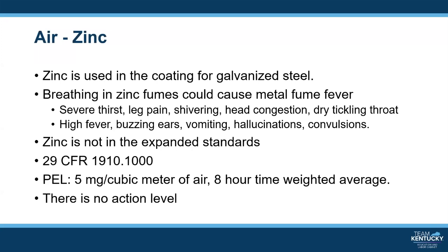Some of you may weld over a period of time and get used to these symptoms, and you may have actually built up an immunity to hide the full effects. If you take a break from welding over the weekend or over a holiday, the symptoms will often come back the next time you weld on galvanized metal. Because of this behavior, metal fume fever is sometimes called Monday morning sickness.